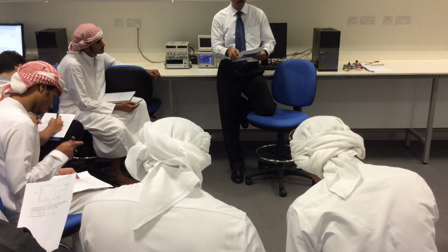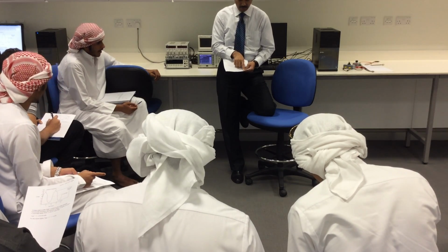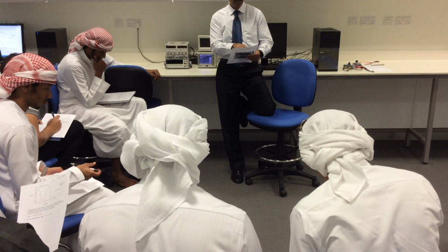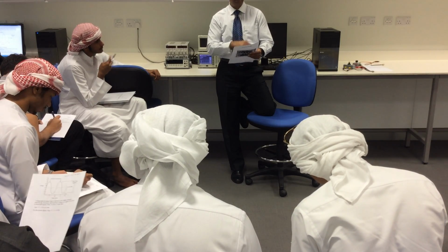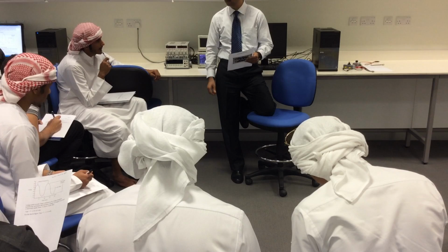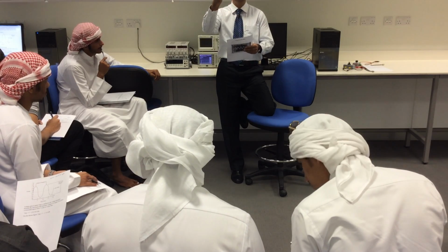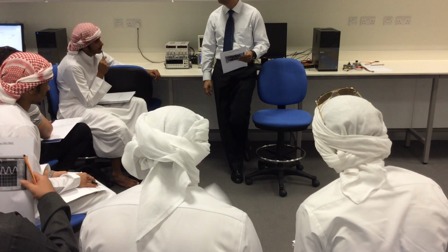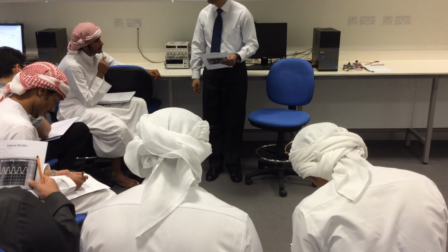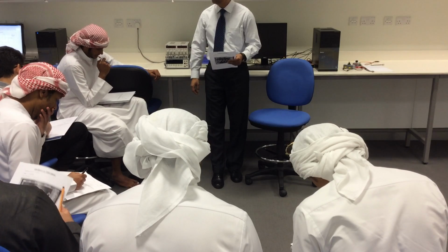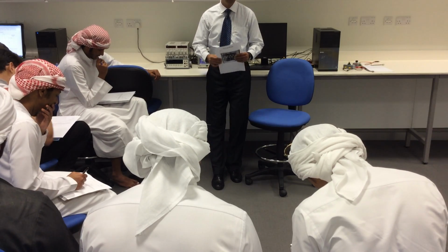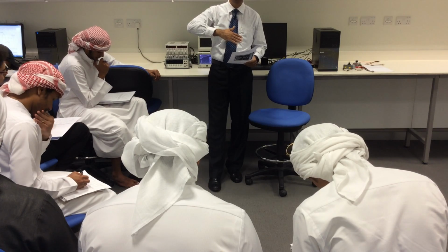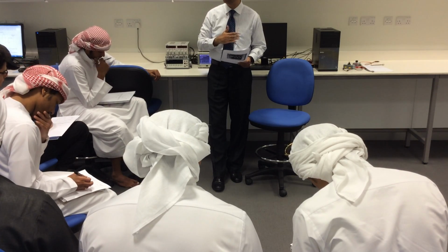And you can actually count it. Starting from 1 volt, so 2, 3, 4, 5, 6, 7. That is 6 volts. So 6 volts is the peak to peak voltage. Whenever I say peak to peak voltage, that means the voltage from one peak to the other peak, the maximum peak to the minimum peak.